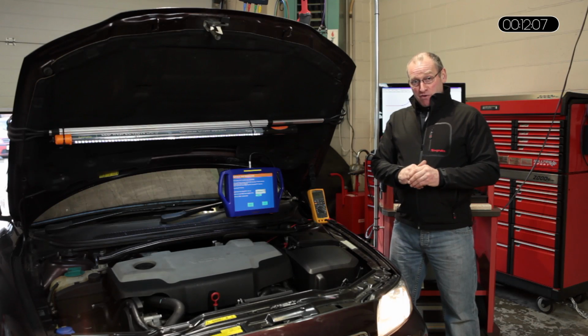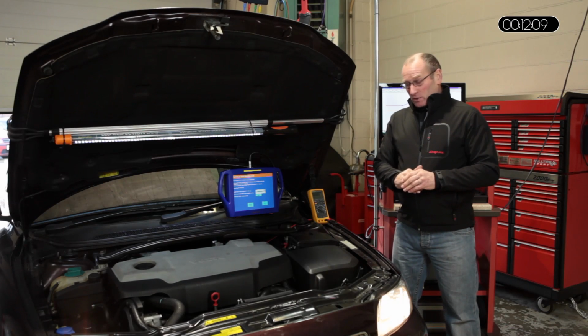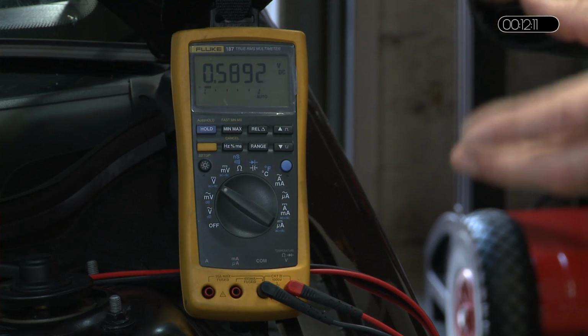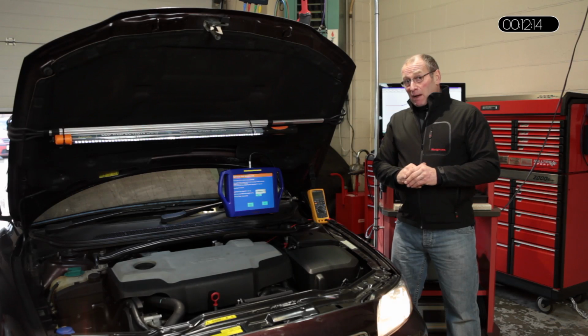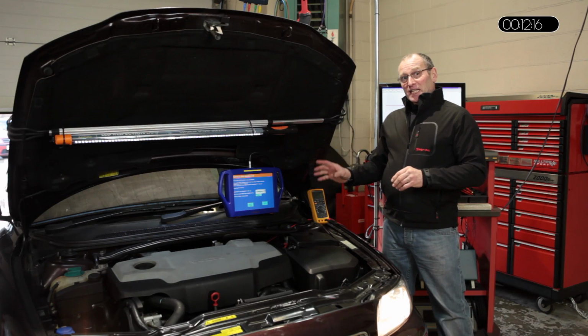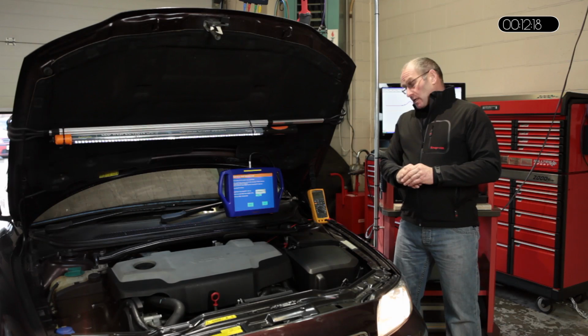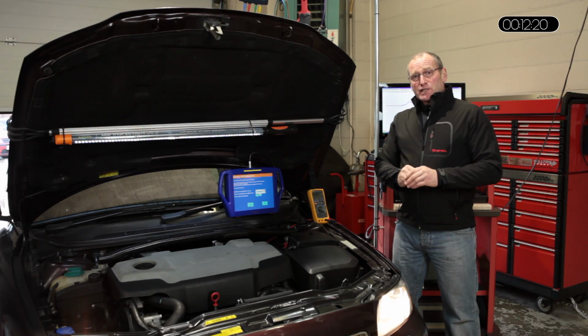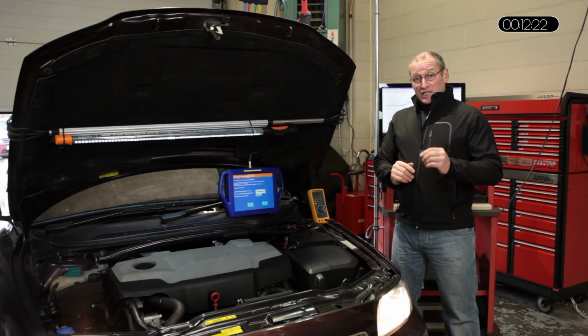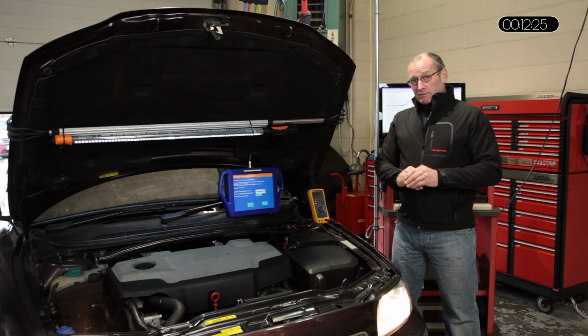the static value, was correct. 0.6, 0.7 of a volt. It's now at 0.58, so it has dropped about 0.1 of a volt having cleaned the DPF. But the plausibility value of the sensor was good, proving that the sensor functionality was not at fault.